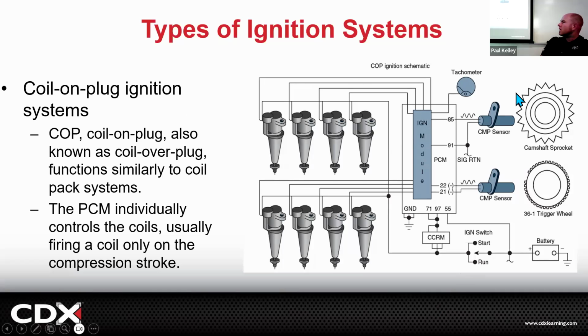All right, so if you look at these, and the car's got 20,000 miles, there's probably no failure points. The car's got 150, 200,000. It could be the coils. It could potentially be a camshaft position or a crankshaft position sensor, right? You could maybe have some wiring.